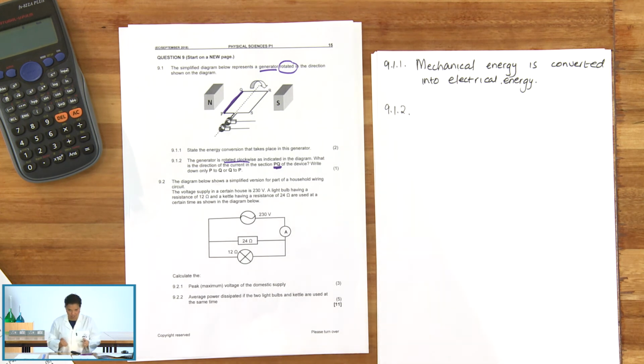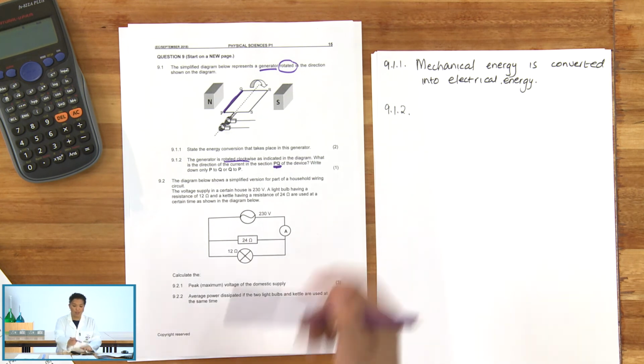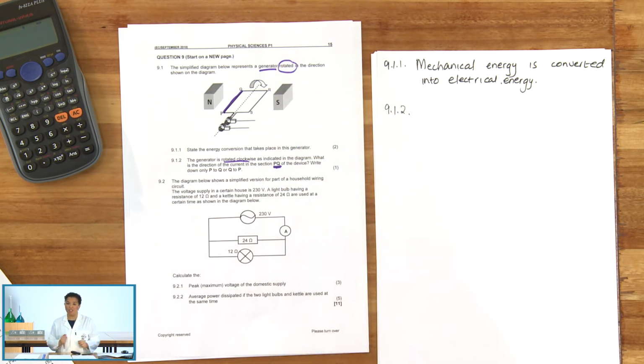We're talking about direction. For generators and motors, we have two rules. For generators, we generate the right answer. So we have Fleming's right-hand rule. And for motors, we remember he motored off and left. For motors, we have the left-hand or Fleming's left-hand motor rule. So what are we dealing with here? We are dealing with generators, so we generate the right answer. Remember our recall technique. So we're going to use Fleming's right-hand rule to determine the direction of the induced EMF or current in this case.